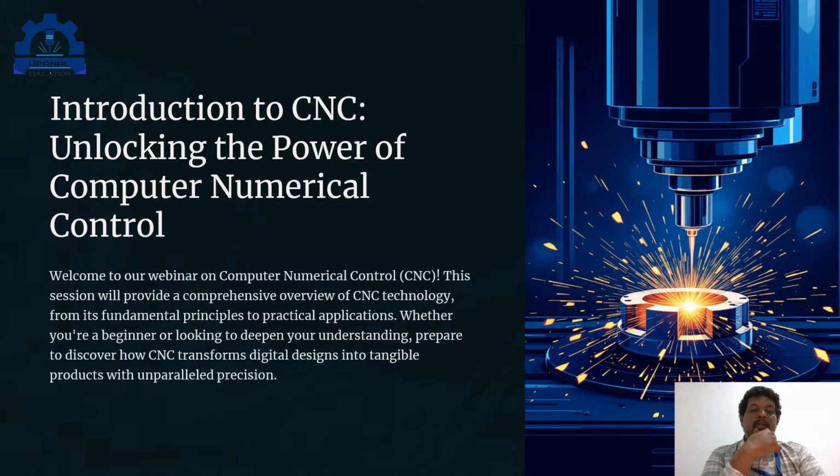What are the axes? I told you about the axes. Normal axes are X, Y, and Z. In the basic three-axis machines, it will be X, Y, and Z, which are known as the linear axes. Now we have the rotational axes. For the 5-axis machines, we have the rotational axes, which are called A, B, and C. Now, what are the coordinates? We have two coordinates which we use in the CNC. That is the absolute coordinate, which means it has a fixed reference, and the incremental coordinate, which has the relative movement.